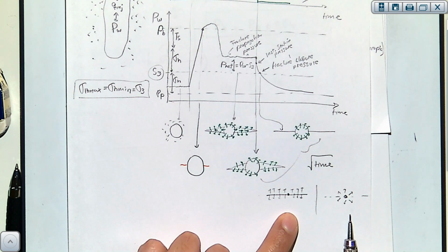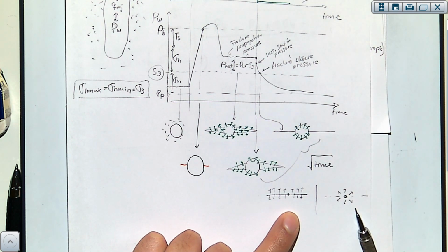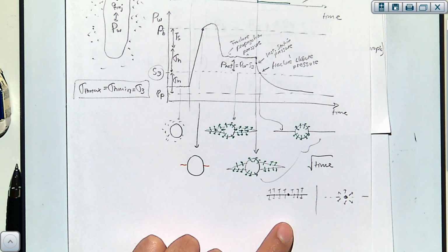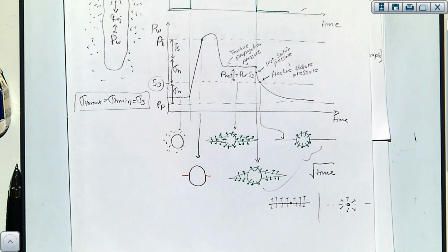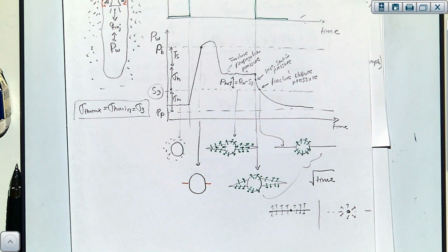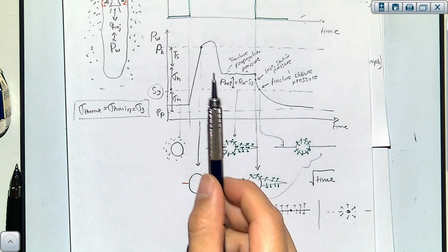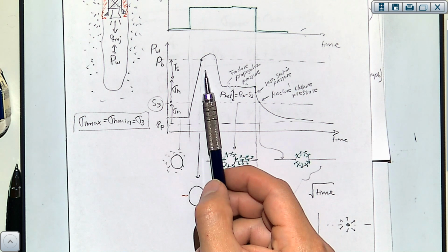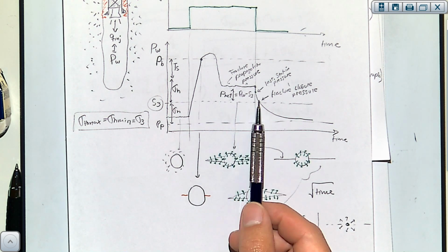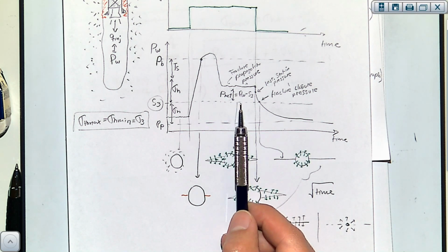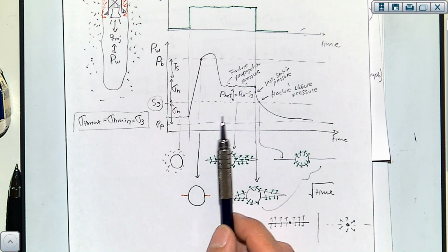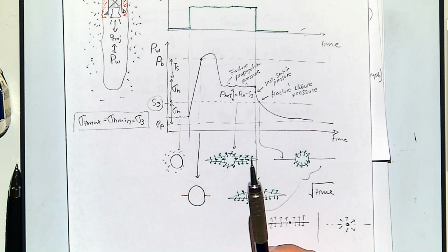if you plot the decrease of pressure with time as a function of the square root of time, you'll be able to see where that point is. And if you do that, you will be able to calculate the fracture closure pressure. But for now, what I would like you to remember from this is that we know more or less what the breakdown pressure is going to be, but this new thing that we have right now for the propagating pressure is going to be the net pressure. And that's what we want to calculate now, at least to have some idea.